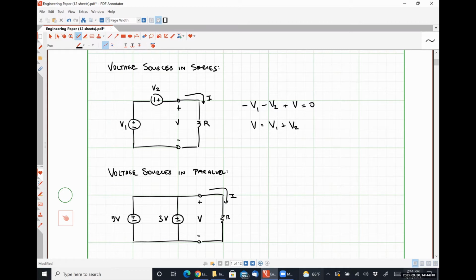Now we could physically make a system like this all day long, right? We could take one fresh battery and one relatively discharged battery, and wire them up in parallel. And what we would see is that one battery effectively works to charge the other one, if that's possible. If you couldn't connect voltage sources in parallel that had different voltages, you couldn't charge a battery. Literally, you couldn't charge a battery. But from a circuit analysis perspective, we have to throw this away. We can't really do anything at all with it.